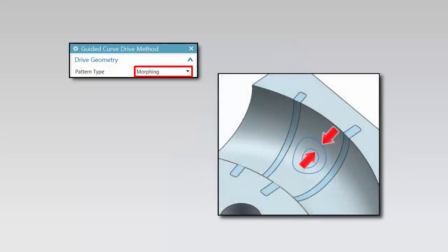You may specify closed curves to define containment loops within the cut area. Although the tool tip is off the part, the tool contact point precisely follows the curves defining the cut area, which is the expectation of the finishing operation. This allows you to use the same curves for tools of different sizes and orientations.